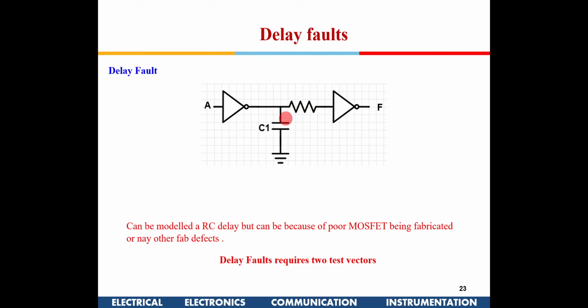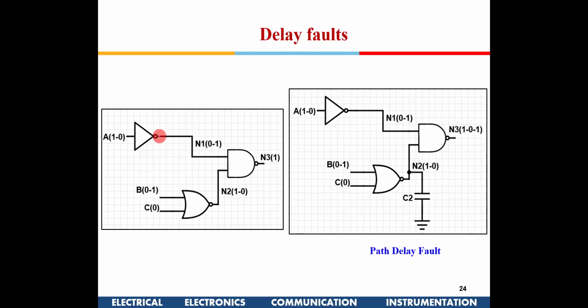I think I have this here. In fact, there is an error out here. Now, if you see here what happens in an actual operation. Suppose this is a circuit in which A is making a transition from 1 to 0, and B is making a transition from 0 to 1, and if the gate delays are normal, then this is making a 0 to 1, this is making 1 to 0. So at any given time one of the inputs is 0, so the output continues to remain 1, no issues with this.